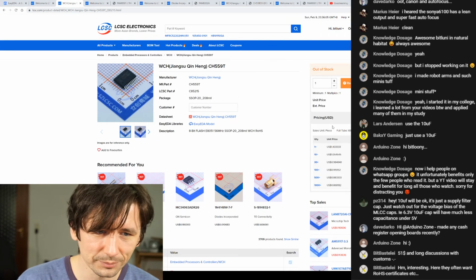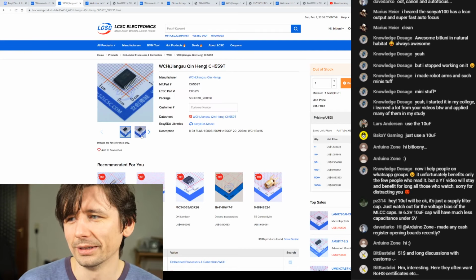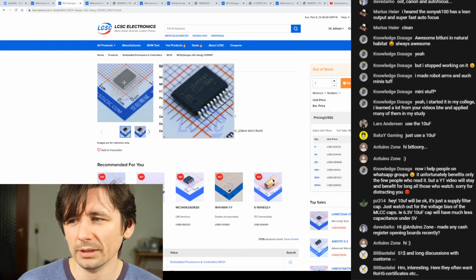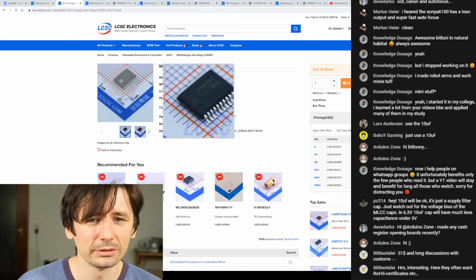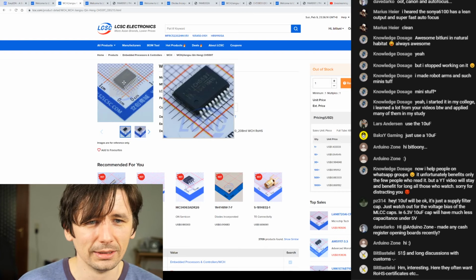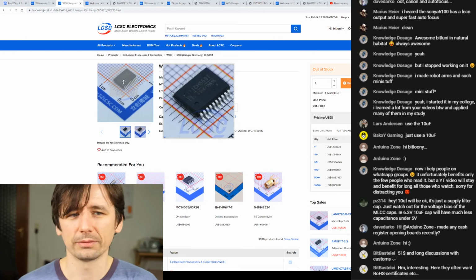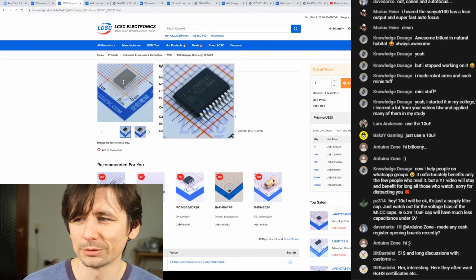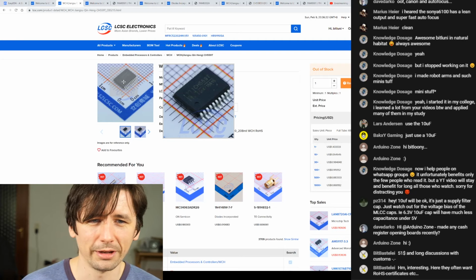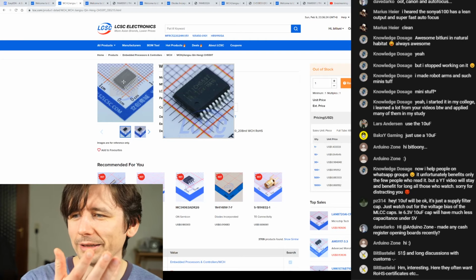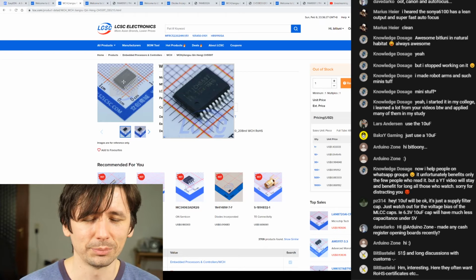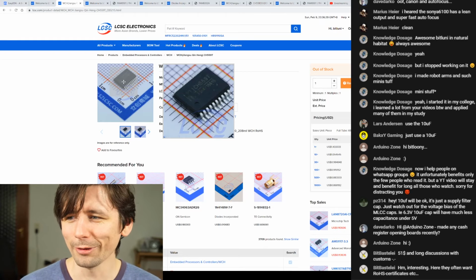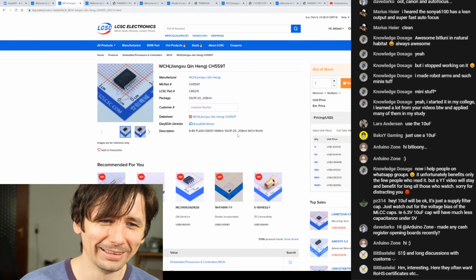I didn't optimize that yet. Okay, so I thought, yeah, cool, I will take this one. So I have 2 host connectors, and the chip doesn't have too many legs and too many problems with solder bridges or anything. So it will be less prone to errors in production. That's what I thought. And then it appeared.